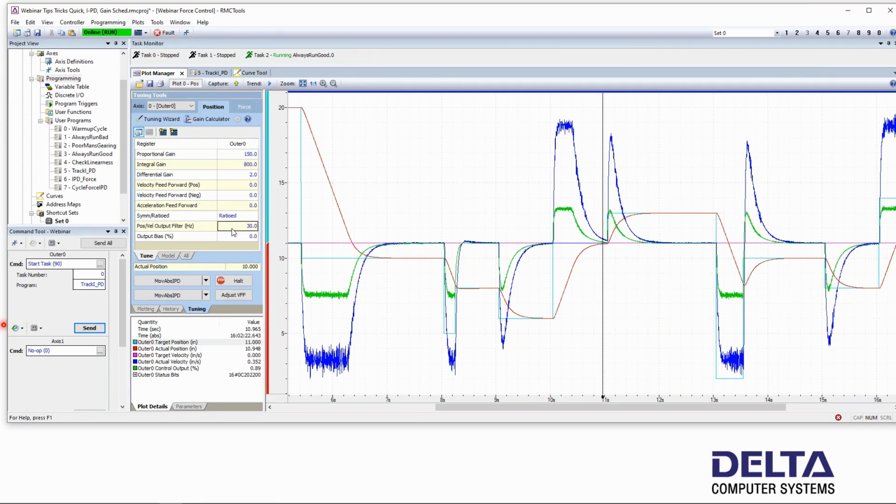Any filter above a kilohertz is basically not going to do anything. We generally have to be a lot lower than that to have much of an effect. Usually hydraulic systems have a lot lower frequencies, and we're typically looking at filtering out the noise. So usually a filter value of about 100 Hertz is a good place to start, and then we decrease from there. A lot of times we can just start at 50 or 30, and that's on a lot of hydraulic systems. So these are kind of general numbers you can pick and choose. Start at 100 or 50. Generally, I go down a little bit more on systems I'm familiar with, like this one here. And in fact, I could probably bring it down a lot more than that if I really had to.